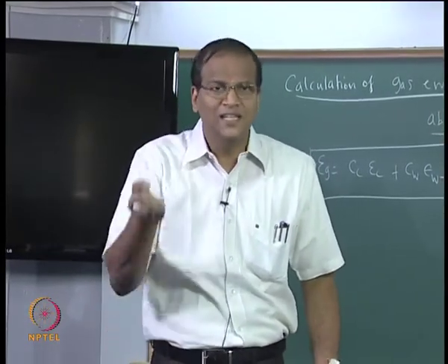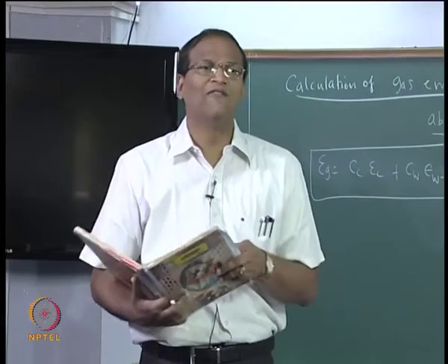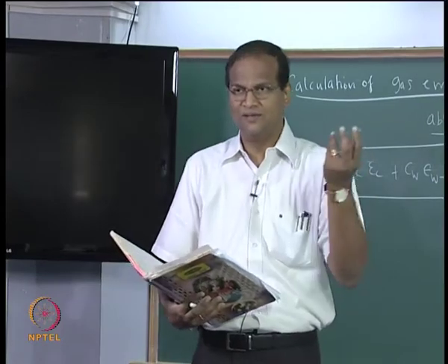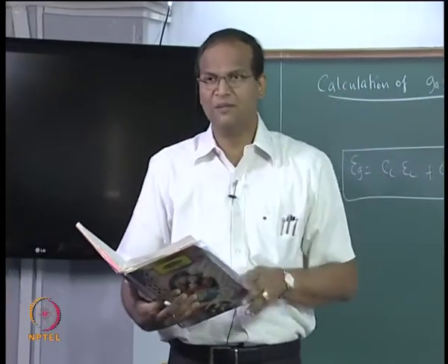For the epsilon g, the gas temperature is very important. For the alpha g, the surface temperature will be very important, because the gas is absorbing from the neighboring surfaces.